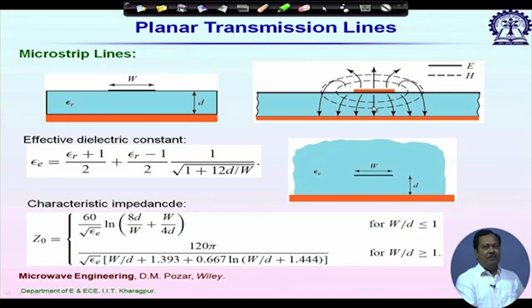So, what do we expect then? Almost no excitation of TE type surface wave mode from the microstrip line, because these two field components are orthogonal to each other, and that is why usually for a straight microstrip line there won't be any excitation of TE mode. But now consider a bend. Several times we will be using different types of junctions like T junctions, Y junctions, X junctions, and microstrip line bends whenever we design any components in printed lines.